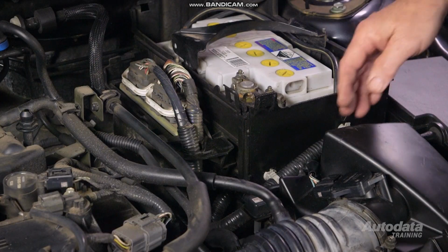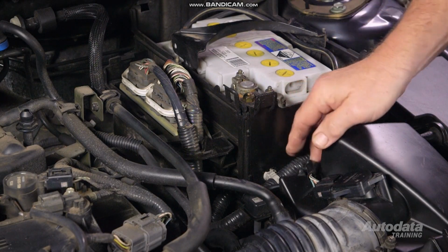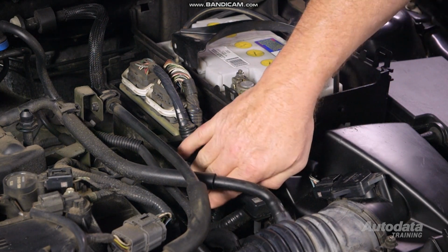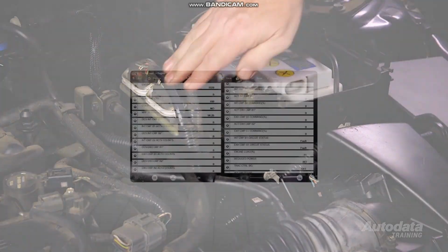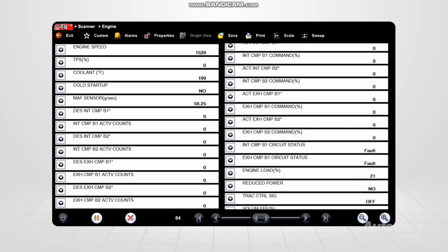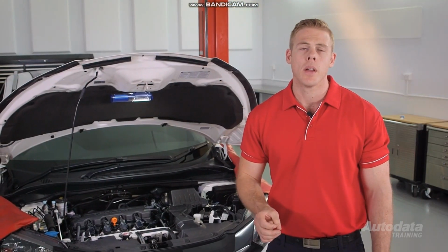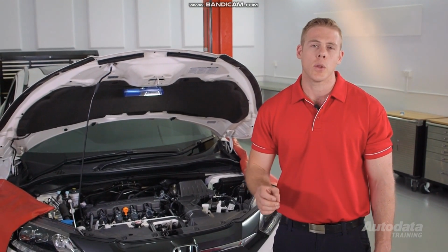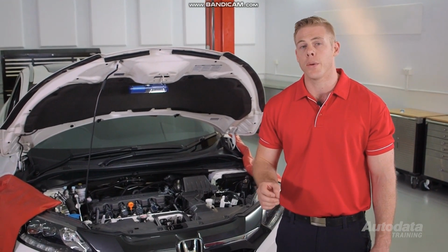It may be necessary to warm the engine, tap on the sensor or module, wiggle the harness and connectors while performing any of the previously mentioned tests. Scan tool data should be observed or recorded for detailed data analysis to rectify any concerns. Take your time and document all your findings when following these test procedures. This will ensure a successful diagnosis of voltage low and